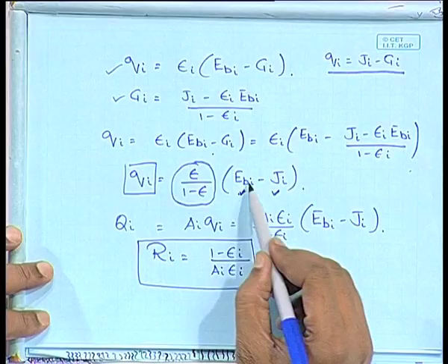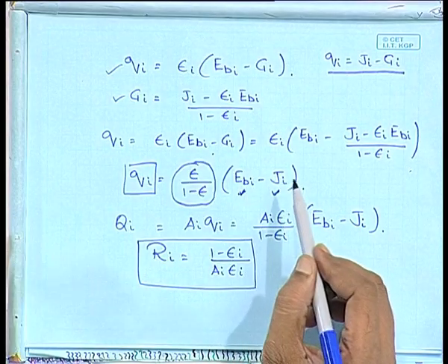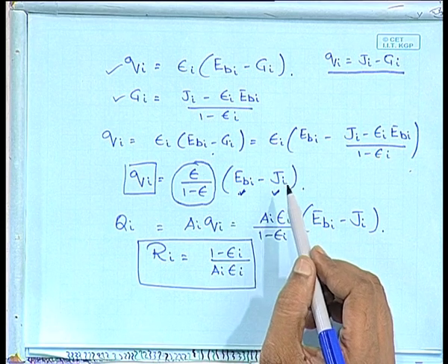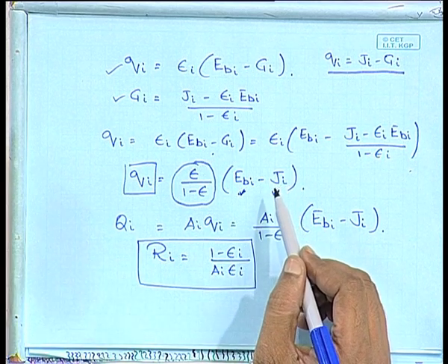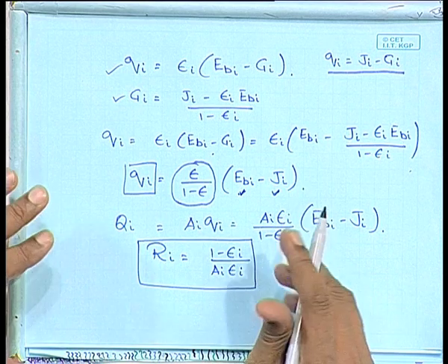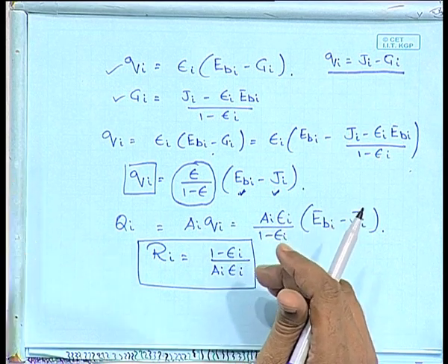So, if the resistance between two potentials is 0, what can you say about the two potentials? They are the same potentials. So, for a black body, E and J are the same, which is consistent with our understanding. But for any other surface, there would be some amount of transfer from the object to the outside, and the amount of transfer is known to you if you know what E and J are.